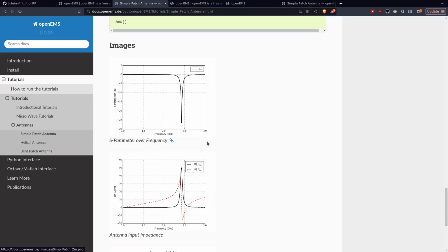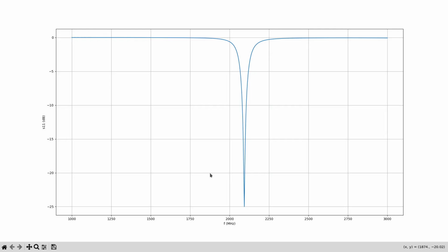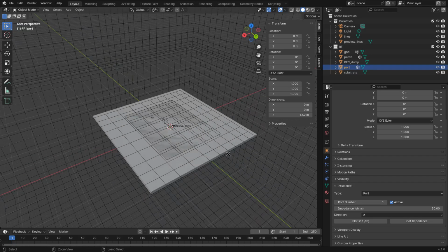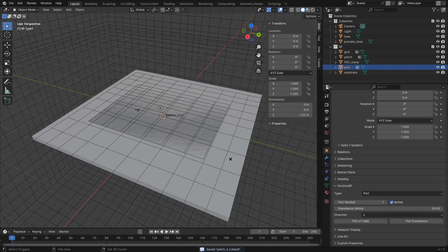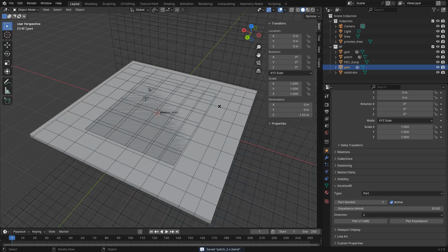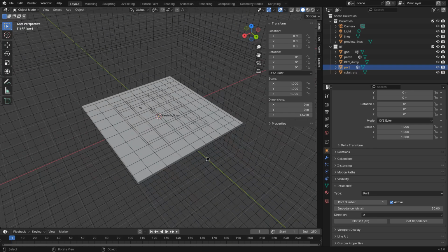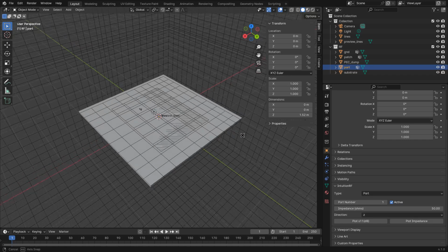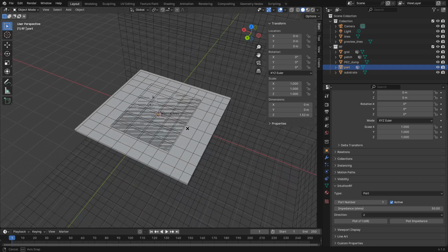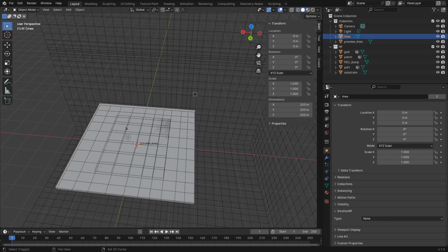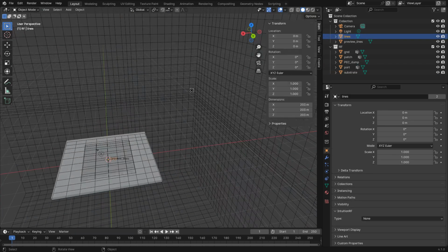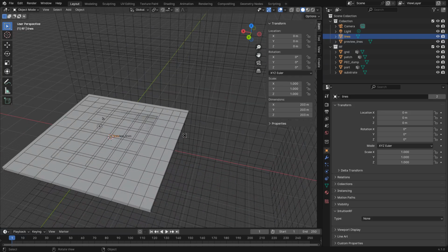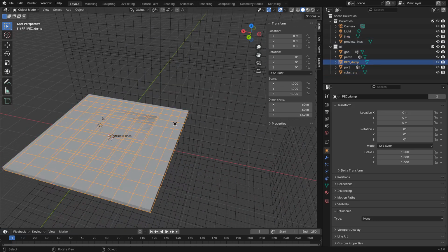As you can see, the antenna in the example resonates higher up, exactly at 2.4 gigahertz. The reason for that is because we lack meshing resolution, especially around the edges of the metal planes. So one way we can fix this is to add meshing lines around the metal planes. You could go into the lines object and add some vertices all around the place, but again, they will not move if you decide to change the antenna geometry.